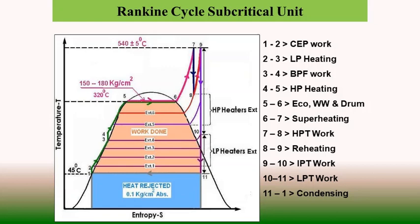Large capacity boilers operate on the Rankine cycle in the subcritical regime, and that's why the arrangement of superheaters, reheaters and other arrangements, including regenerative feed heating, is preferred for the purpose of cycle efficiency. They are generally operating at a pressure of 150 to 180 kg per centimeter square with a saturation temperature around 340 degrees centigrade and superheated steam temperature of plus minus 540 degrees centigrade.